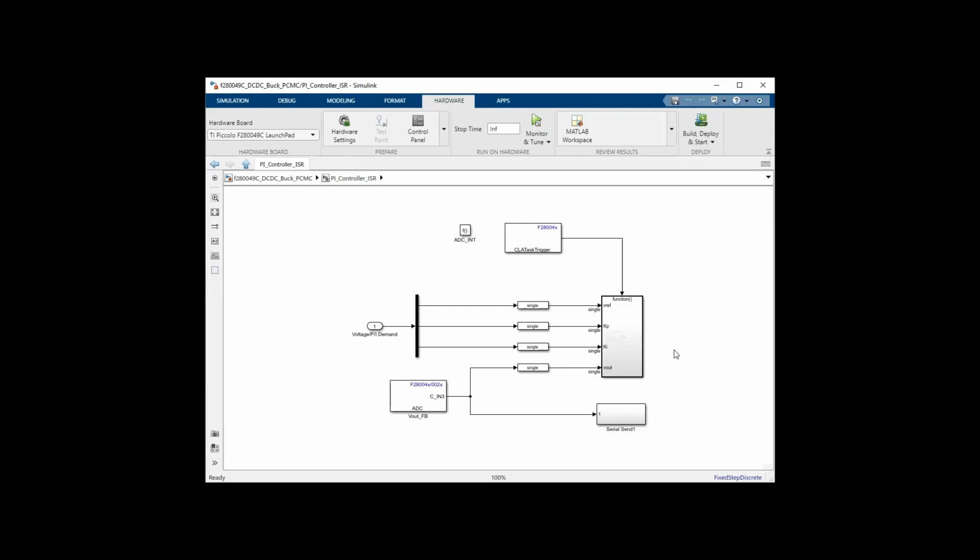Given the high sampling frequency of 200 kHz and also the need to support the two model approach for host target communication, the CPU bandwidth was offloaded to CLA to execute the control loop. This enabled the CPU to achieve the host target communication at such high sampling frequency.